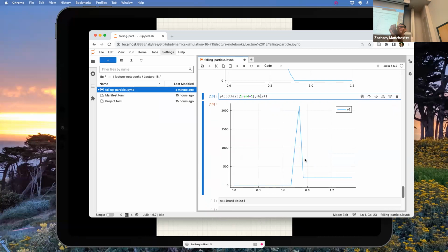So if I'm simulating at 20 hertz, all I know is that somewhere in this time step, like time step 19 or something, I hit the ground, right? So this is that spike, but notice it's finite. It's finite because I'm smearing that impact event out over the time step, right? That's what's happening. So I only ever resolve it to within whatever my time step is.